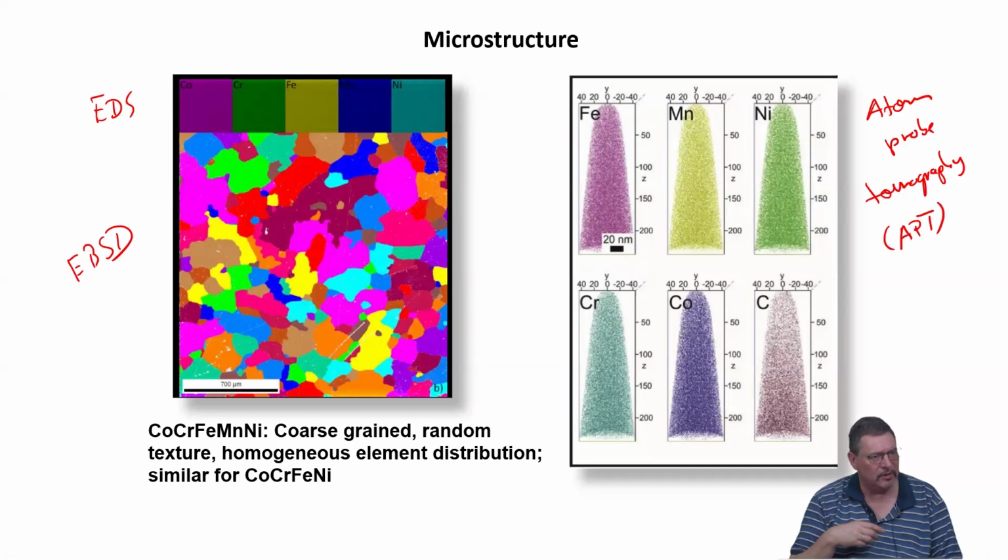So we are sure that on all length scales of the microstructure, from atomic, atom probe tomography, to really grain size length, which is of the order of many, many micrometers, we have a very uniform, homogeneous material in terms of its chemistry and chemical component distribution, with a random texture, so no strong anisotropy in terms of orientation of grains. So ideally to do diffusion measurements.